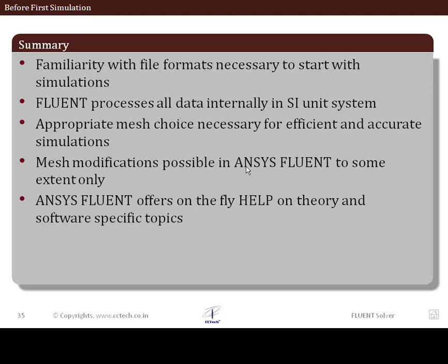And you can choose the appropriate mesh for efficient, accurate simulations. A structured multi-block flow aligned grid is the best choice, but it's complicated to generate. Usually with the hardware that is available here, we can deal with a very fine unstructured mesh and rather concentrate more on the solution process and the analysis part.